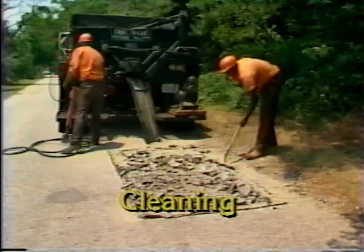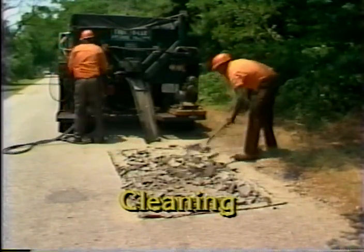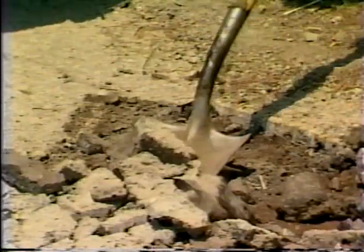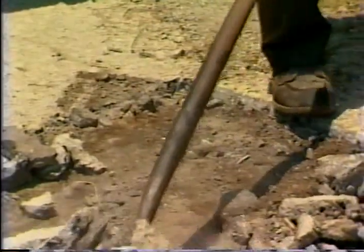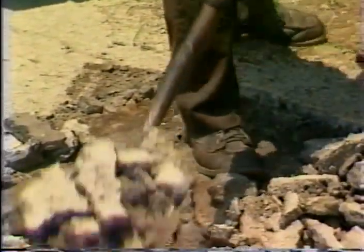The third step in the patching procedure is cleaning. This step involves the removal of all loose material and water so that a clean surface is available for the bonding of the tack coat and patch material. Remove material down to stable pavement or base material.